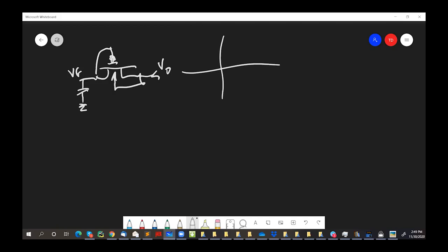Okay, so here is the pseudo resistor. It's a PFET. And like I say, you've got the capacitor over here. You can see this, right? And here is the node you're actually driving. You're driving this by the amplifier. Here's what we call the floating node, what I call VF there, and here's VO. And what we have to do now is tie the bulk to this side. That's what we call a pseudo resistor, where we have this kind of exponential IV relationship.